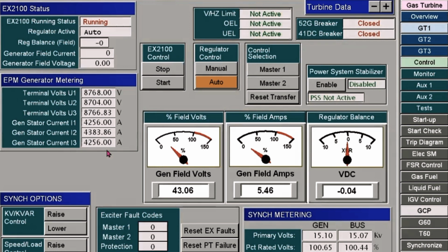The I1, I2, and I3 magnitudes must be equal in any case, and this type of unbalancing may occur due to system disturbances. For example, if on the transmission side any one conductor has dropped to the ground, that conductor will show very high current.